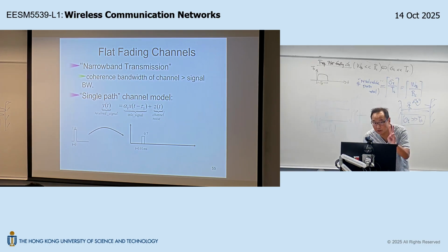So there are two independent random processes in the channel. One is the channel noise. The second is this fading coefficient. These two things are random. Okay? So that is the additional effect due to this so-called frequency flat fading effect. This is coming physically from the multipath. Okay? So physically, this is coming from the overall effect of the multipath, the combination of constructive and destructive superposition.